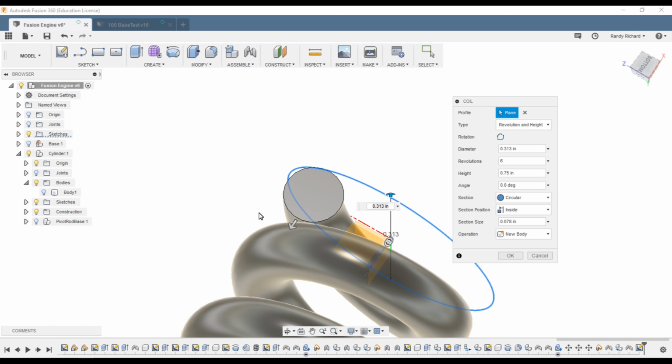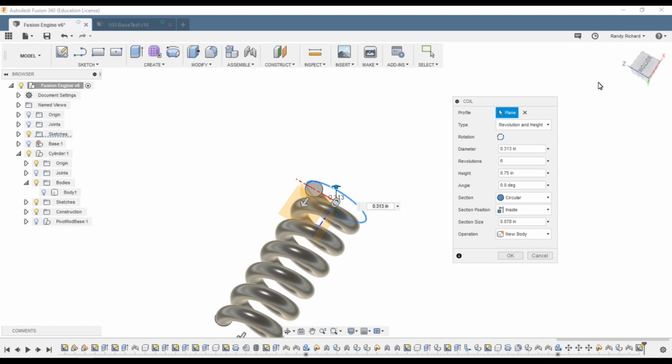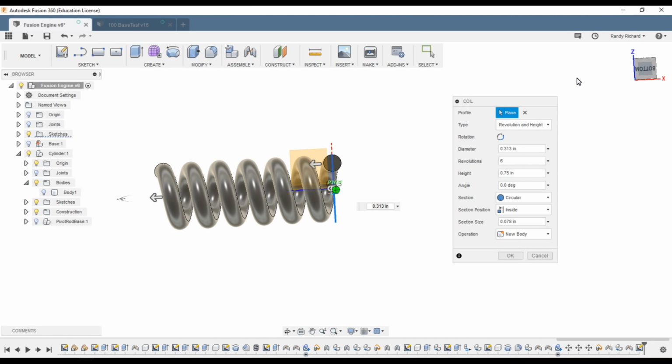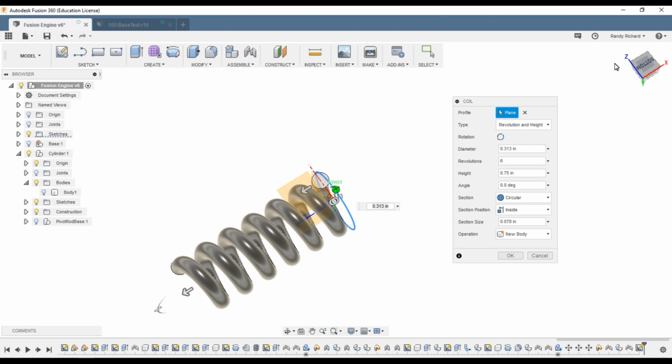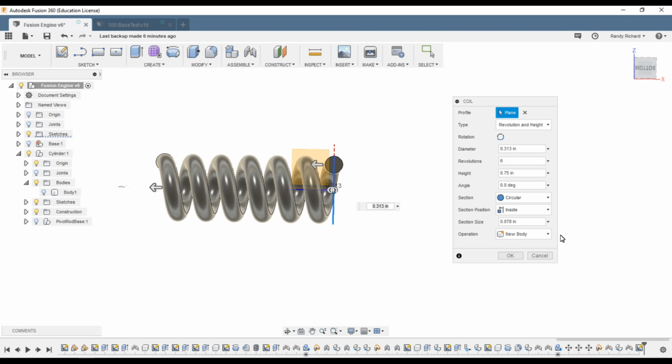Okay, let's leave the spring on the outside of the line because that's our diameter. That's the way the outside of the spring is 5/16, because that circle we drew is 5/16, and that's what we want because we want to fit into those little caps.